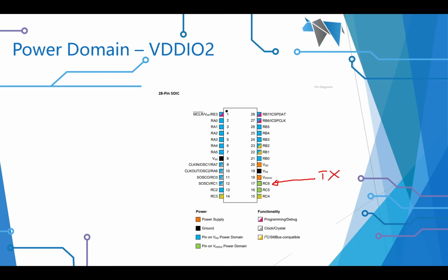that port. But there is something also very, very important, which is that this diagram for this particular chip has what's called power domains. You apply voltage to the VDD. I've supplied 3V3. You could supply 3V3. I don't care which one you do.